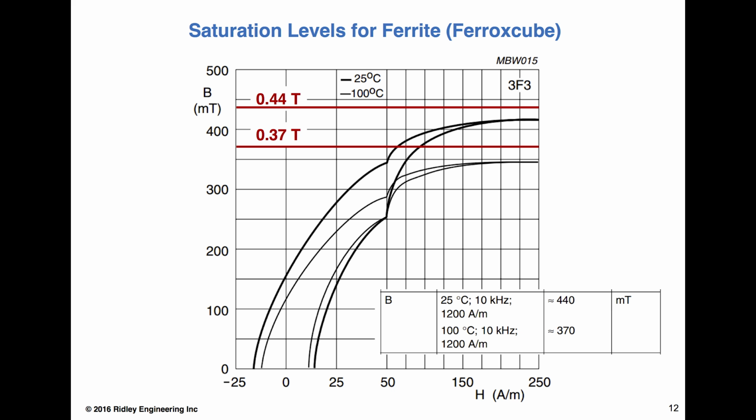Well, there's always been the equation that if you want to up the Bmax, you're going to up the dissipation. I haven't seen that violated. So if they're running nanocrystalline, they're running at 1.2. Yes, it's probably much better dissipation than a steel would be, but I sincerely doubt that it would get even close to challenging the ferrites. So I'm not seeing those in switching power supplies, maybe instrumentation applications.